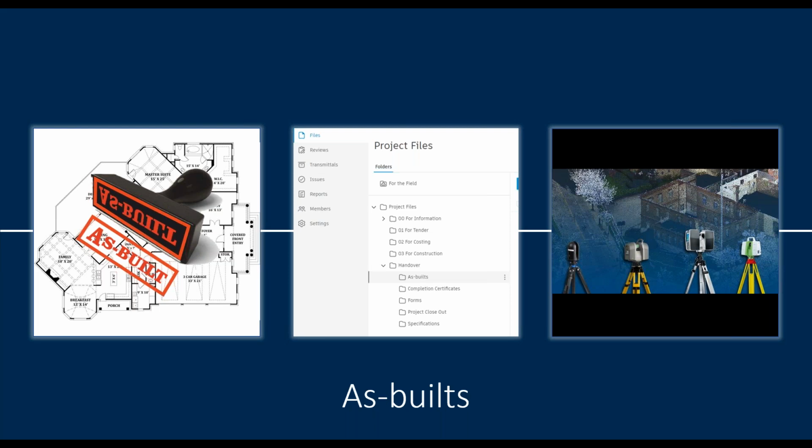And this is particularly useful on renovation and alteration projects. That's just because typically the as-built drawings mean nothing. If you've worked on an alteration or a renovation project, you know that you can't really trust those as-built drawings. You end up going to site with your measuring tape or your laser meter, measuring up, writing it down, just to verify if the things on the as-built drawings is actually what is on site before you can start to do your designing. And so in a BIM workflow, something like 3D laser scanners would be used.